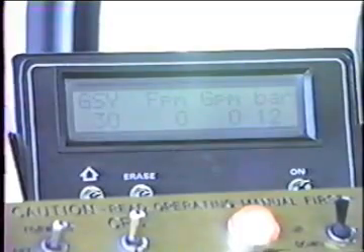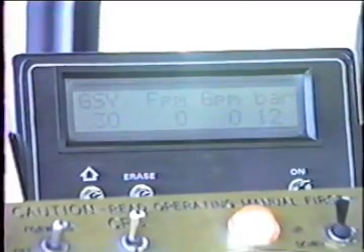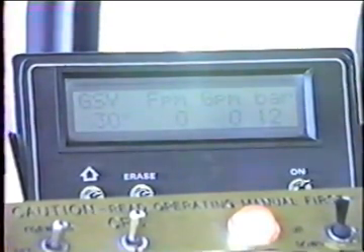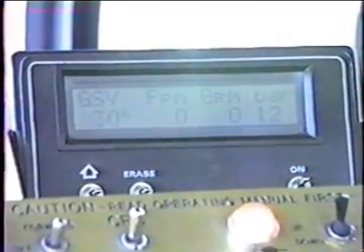The computer now is seeing we want 3/10 of a gallon per square yard. It'll see the travel speed, the feet per minute, as soon as we start to move. It is reading the bar width from the control panel. Now it will calculate the required GPM and adjust the asphalt pump to that. And of course it does that 100 times a second every second.